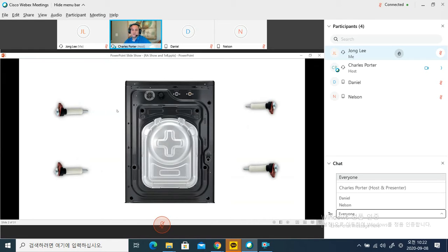you'll want to do a good thorough physical inspection, pop this back plate off, pop the top off, and really look around, make sure nothing is damaged from those being left over. So that's the first thing you want to check, especially if it's a newer unit. If they've had the unit for 2 or 3 years, there's no way those shipping bolts will be back there because this thing would be destroyed at that point. But if it was just delivered a few days ago, a week ago, maybe even a couple of weeks ago, if they haven't used it too much, you want to check for those shipping bolts right away.